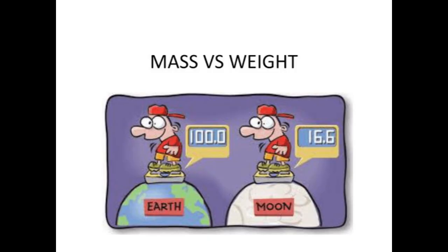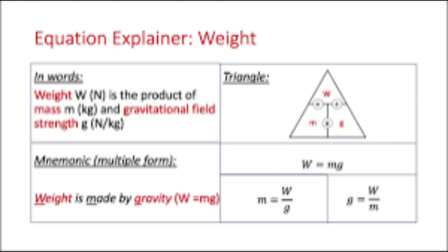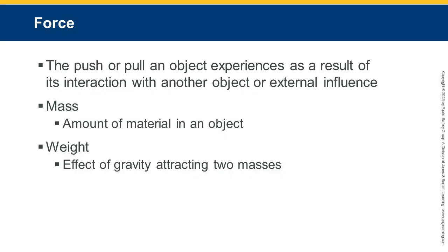Here's a quick tip. The difference between mass and weight is one of the reasons metric units are a lot easier for calculating forces. Metric keeps things clean and avoids confusion. That said, for most rope rescue work near the Earth's surface, we can kind of use mass and weight interchangeably. Just remember, weight equals mass times gravity. Gravity's always sneaky, so don't forget it. So, when you're rigging a system and thinking about how much pull or tension a rope will face, remember, it's all about the forces acting on it, and knowing the difference between mass and weight helps you make smarter, safer decisions.